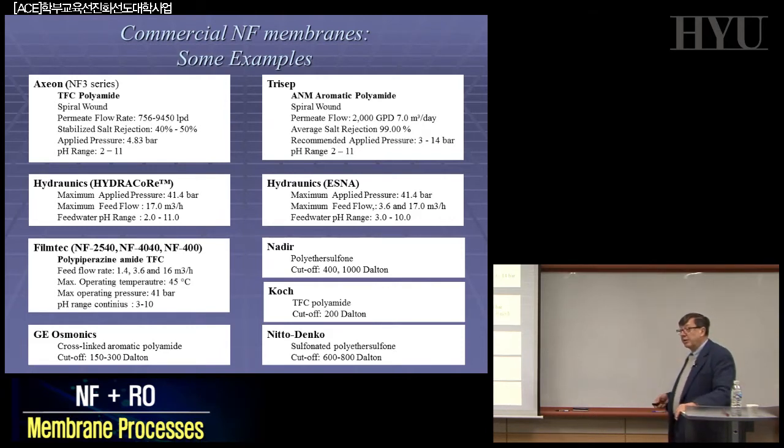So don't be nervous if you don't have 99%, because there are some specific applications where we need this kind of selectivity for salts, monovalent, sodium chloride, etc. But when you have this selectivity for sodium chloride, the selectivity for sugars, some amino acids, some dyes, or different kinds of drugs, antibiotics, etc., can be just 40%, maybe lower. In some cases it can be just 3% or 10%, but amino acids 90%. So you can separate some contaminants from your final product using this kind of system.